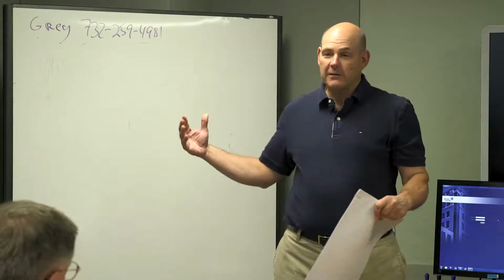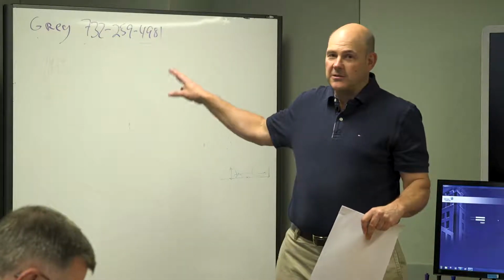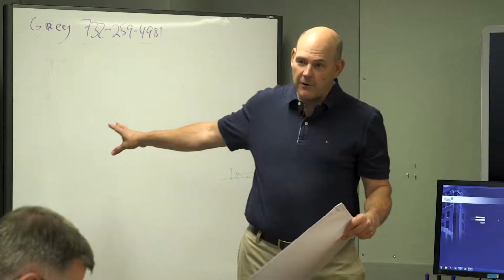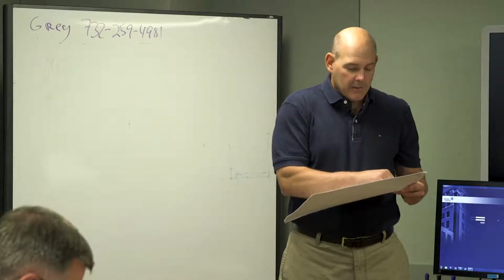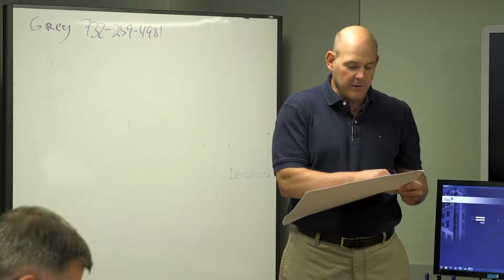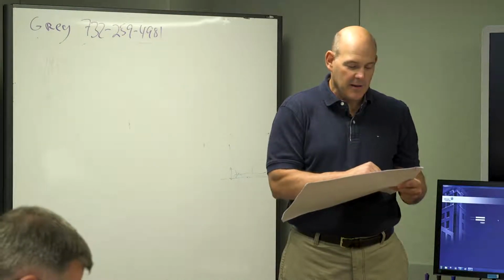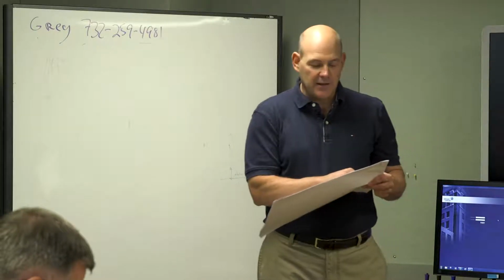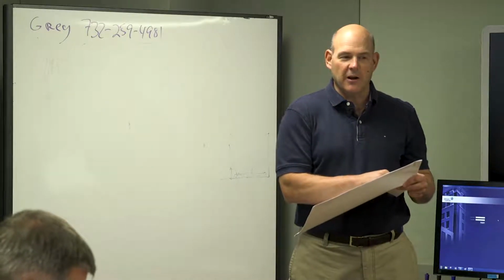Okay? So this is why the beginning of this was important, that you understand software and hardware. So the one that says PCHWP3-S, that is status. That is telling you that the pump is running.